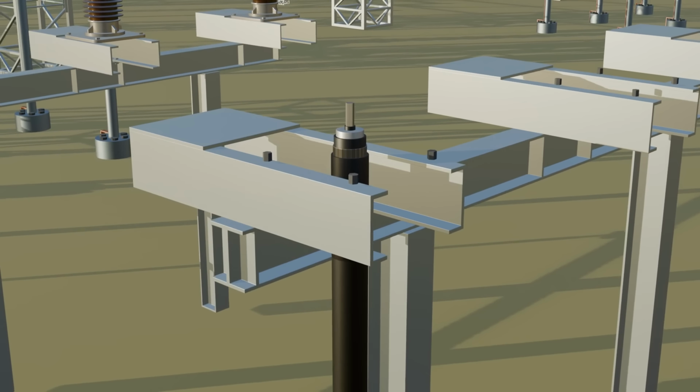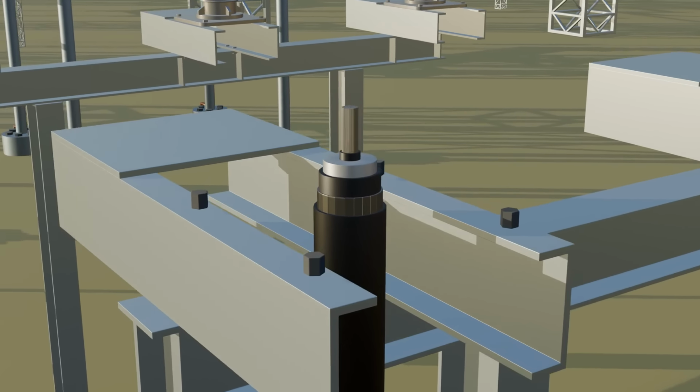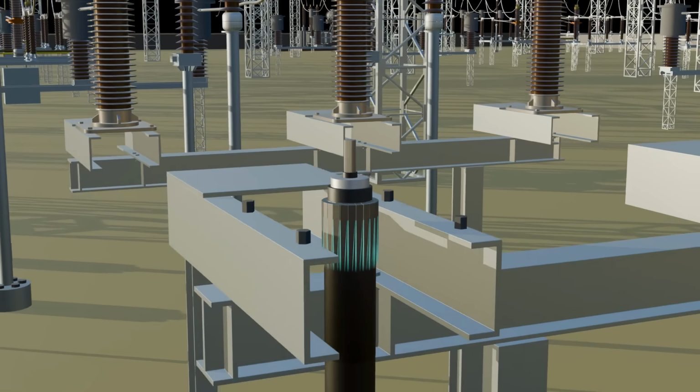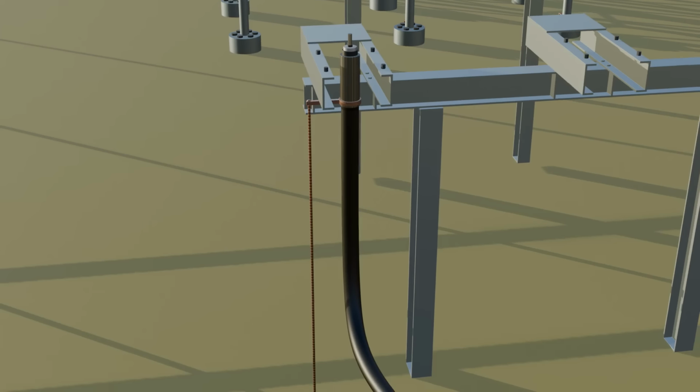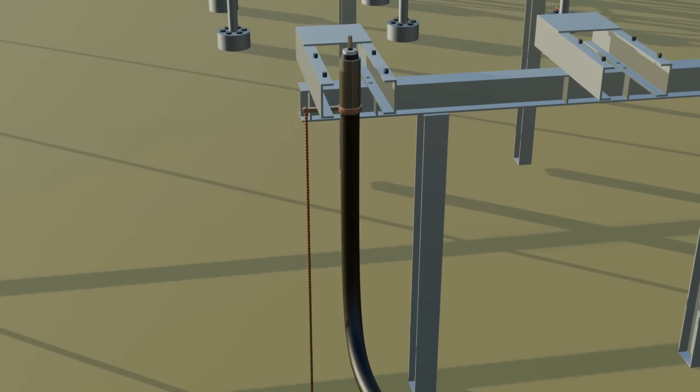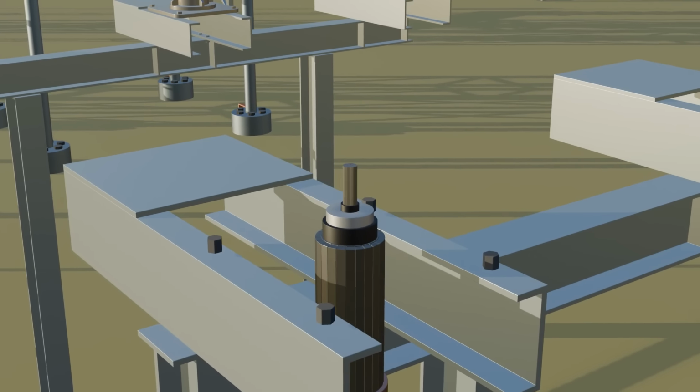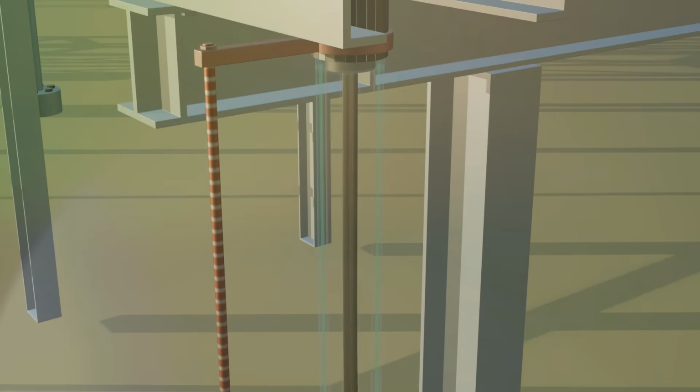When the cable reaches the substation, the metallic screen is properly earthed. If induced voltage or any faulty condition occurs inside the cable, this screen safely carries the unwanted current to Earth. When high voltage transmission takes place through these cables, major engineering challenges appear.